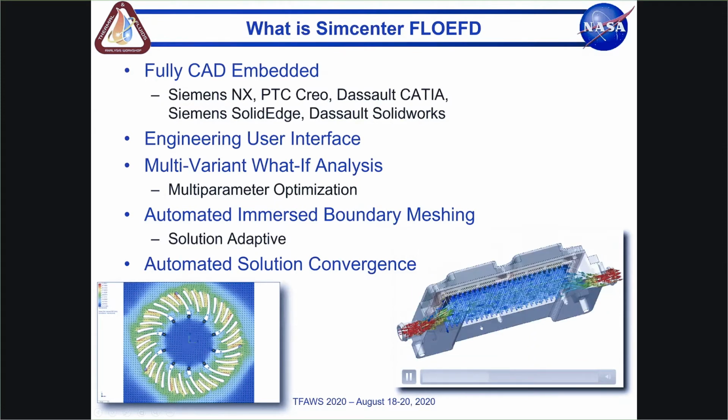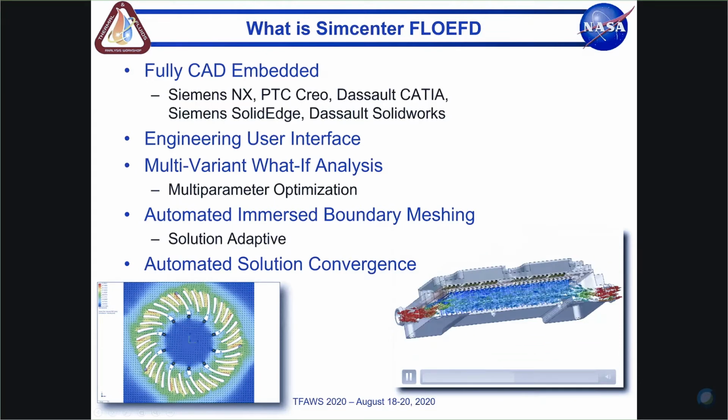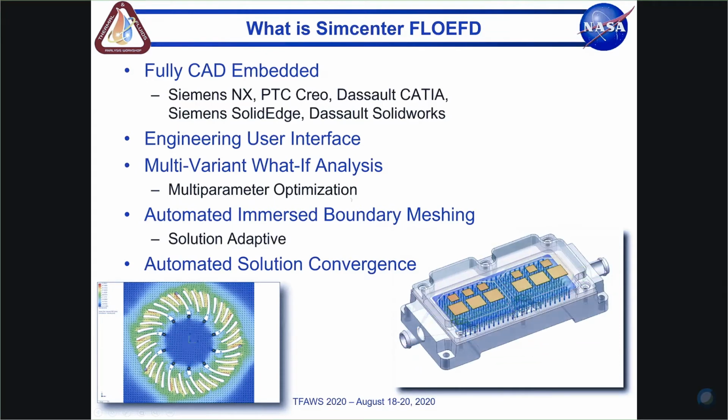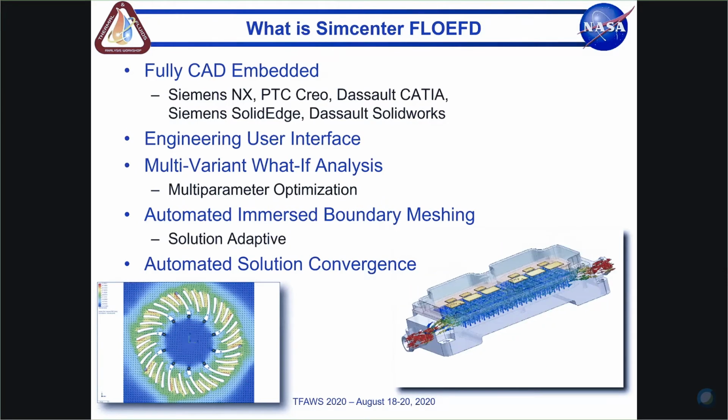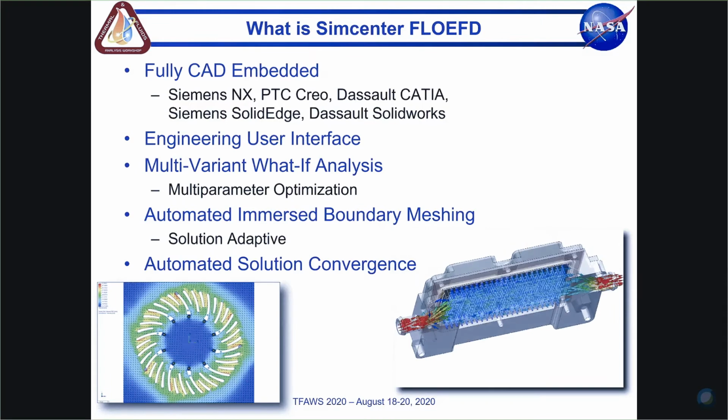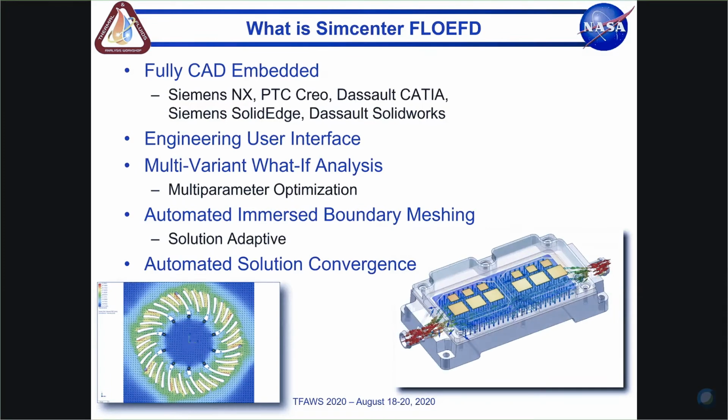We also bake in multi-parameter optimization into the software. So maybe we don't want to go through the effort of deciding if we want staggered or inline pins or what size they should be, what diameter they should be, what flow rate we want. We'll just let an optimization tool solve that for us. So we have a very efficient way of doing that.